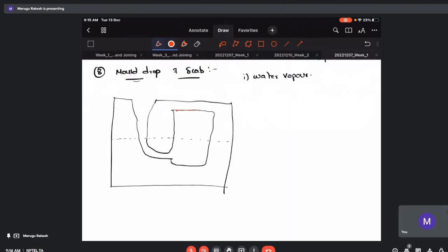It will form water droplets, and it will loosen this part of the mold wall. When the mold wall is weakened, and there is differential expansion of the sand, which induces some compression and shear forces, under these conditions we can really get a crack in the mold wall, and there is also the addition of its self weight.